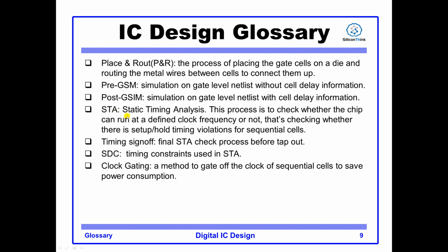STA stands for static timing analysis. This is the process to check whether the chip can run at a defined clock frequency or not. In detail, it checks the setup and hold timing violations for sequential cells.